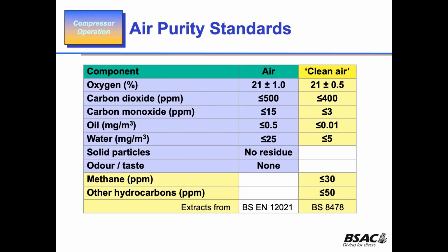And so what they don't want is to be putting that stuff into a cylinder that hasn't been oxygen cleaned, right? Not so much worried from 40 down, that's not too much of a problem. When you go above 40, like 45, 50, 60, 70, 80, 90, 100% mixes of oxygen, then it becomes very, very critical.